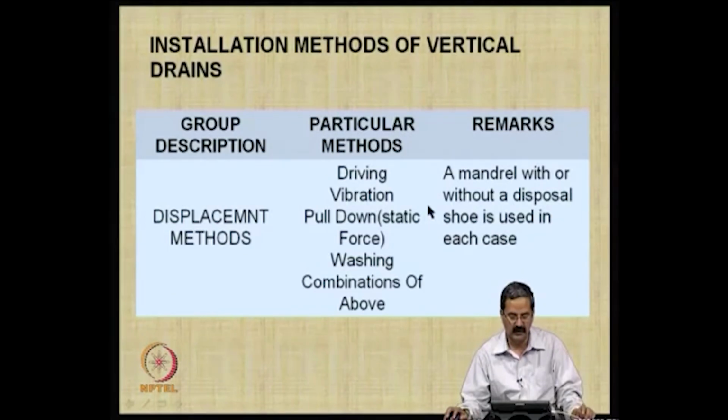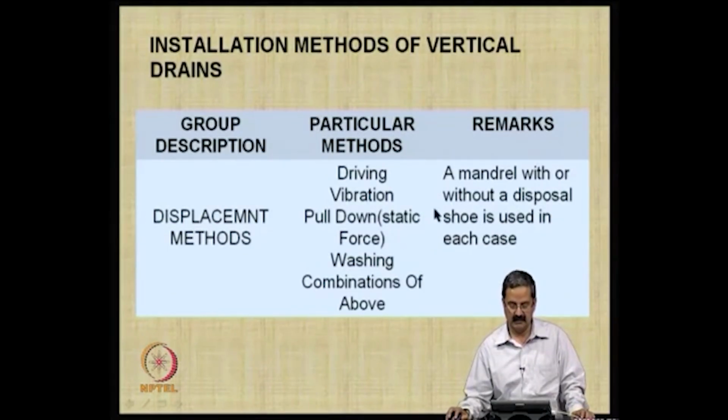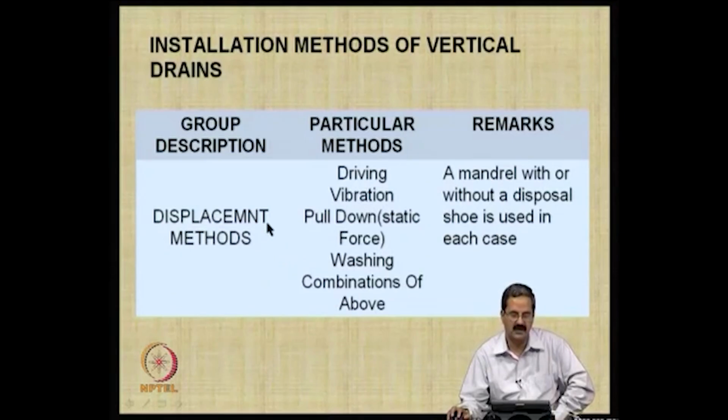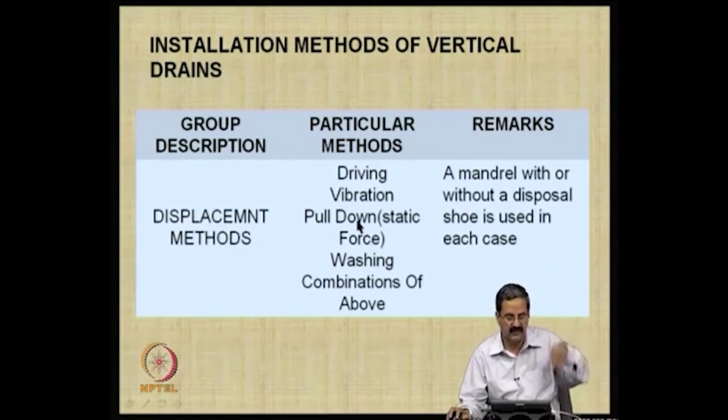So, how do we install it? There are some typical methods, like displacement methods, where it can displace the soil. Of course, the soil is so soft, it can be displaced nicely, and the particular methods you have are driving, vibration, and pull down using a static force.